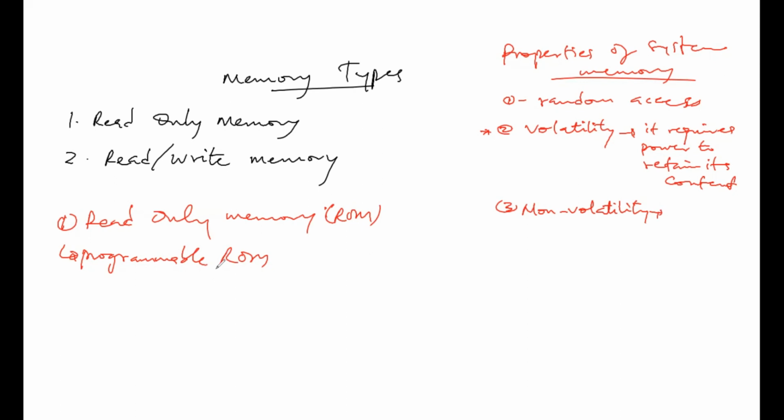So in programmable ROM, a fuse is associated with each bit cell. So to read a 1, the fuse has to be on. And to read a 0, the fuse has to be turned off, that is burned, B-U-R-N, by sending high current. Okay, so once burned, the programming or writing process is irreversible.